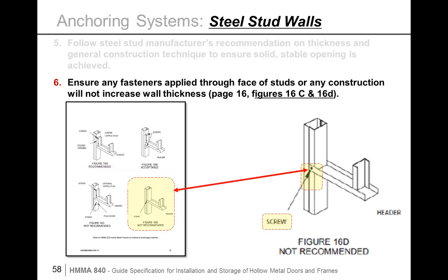And inspecting job sites, reviewing back charges in the steel stud, wood stud areas, one of the common issues is the frame throat dimension is incorrect at the job site for some reason. And back charges occur. And this could be related to either trying to insert the drywall, or it actually could be showing up in defective face surfaces where finished paint will show that there's bubbles in the surface.